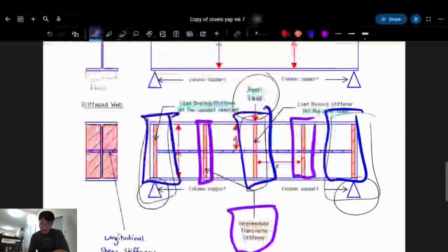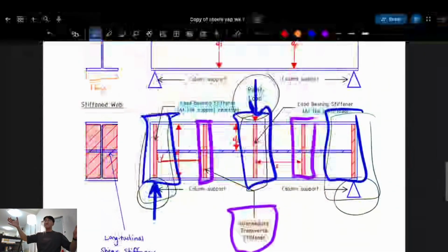In terms of shear forces, the highest ones are going to be at the load-bearing stiffeners, right? It's going to help the beam not completely crumple there. The intermediate ones are more because the spacing of these matters. If you space them more regularly, they're going to assist in resisting that crumpling action. So it's resisting shear.